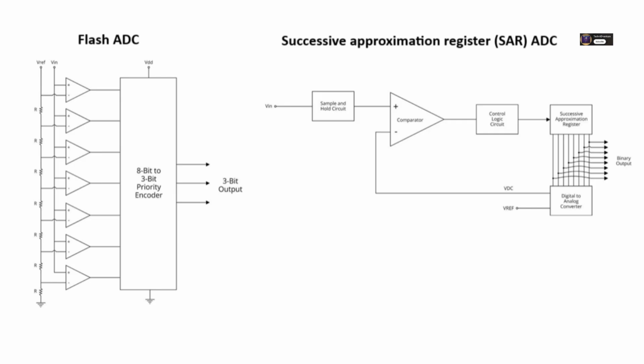These actually measure time. They use an op-amp circuit called an integrator to charge a capacitor with the input current for a fixed time, and then measure how long it takes to discharge that capacitor using a known reference current. Measuring time to measure voltage. Interesting. Yeah, a common variation is the dual slope ADC, which integrates the input up and then integrates a reference voltage down.